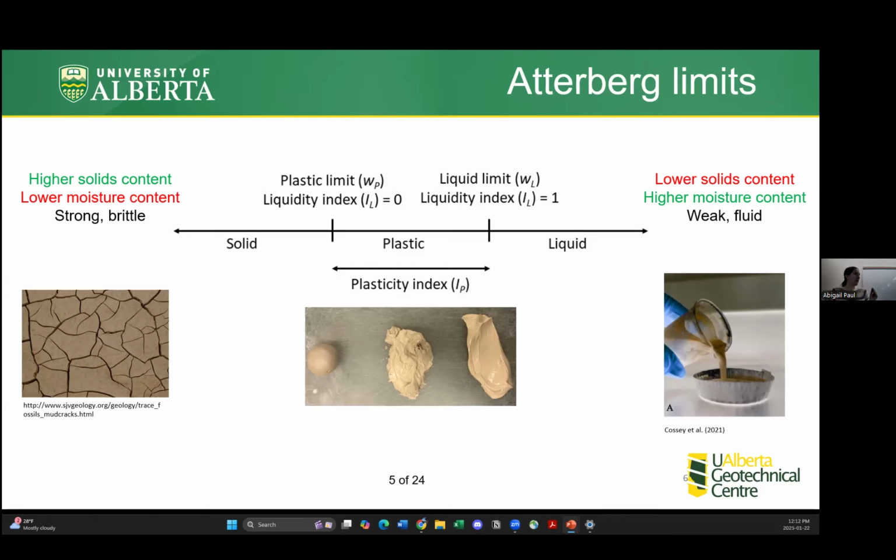The Atterberg limits define the transition from one behavior type to the next. So liquid limit between the liquid and plastic behavior, and then the plastic limit from the plastic to brittle solid behavior. We also define the plasticity index as the difference between the liquid and plastic limits.